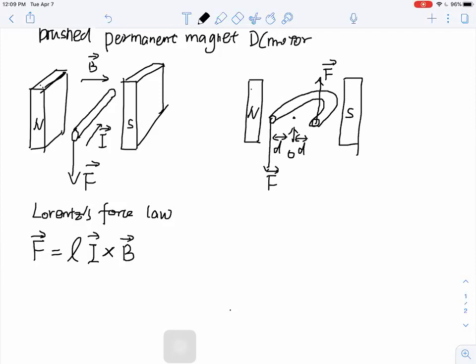And from what we learned in other mechanical classes, we use T to represent the torque of this metal loop inside of this magnetic field. Torque T is going to equal, since we have a couple of forces, right, force and then a point that this loop is rotating about, and we know the distance, so we can find that the torque is going to be 2 times dF. That makes sense. That's the torque about O.